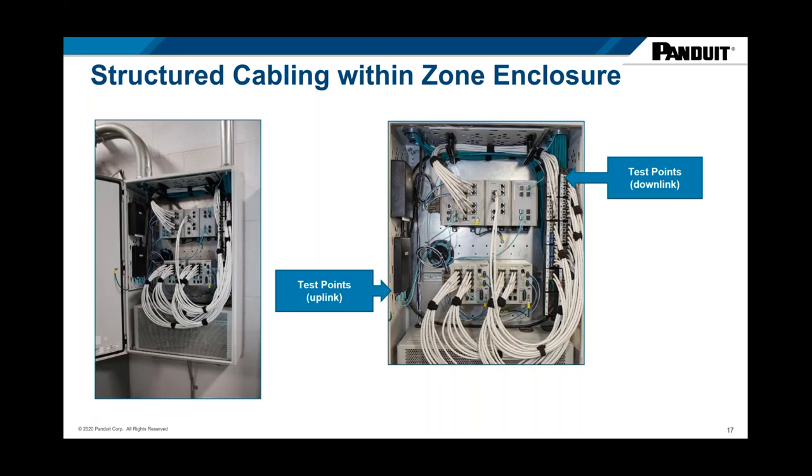And what we're showing you here, if you look at the diagram, the aqua colored, the thin cable in this image are the fiber backbone uplinks up to the layer 3 switch in the IDF, and the green cabling that you kind of see in the background there, that's what we were referring to as the horizontal cabling or the downlinks that are connections to control panels or machines.